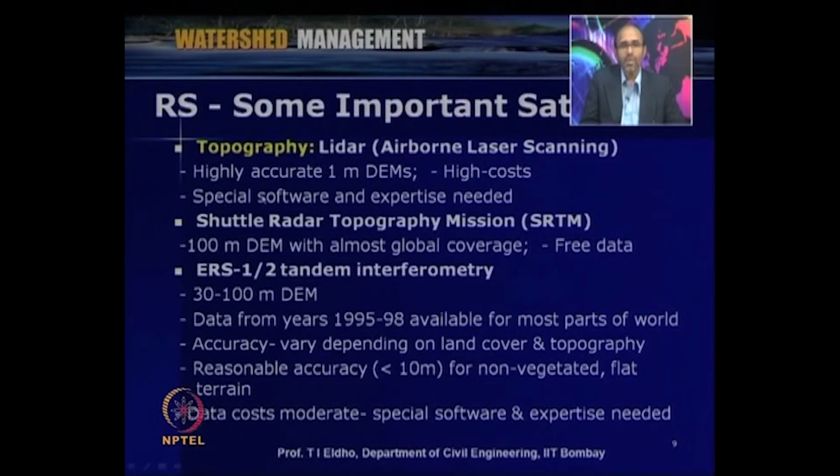For high resolution data we can use LIDAR data. It is highly accurate, even up to the level of 1 meter. So, we can get 1 meter detail elevation models using this data, but the cost will be high, and special software and expertise are needed to process such data.